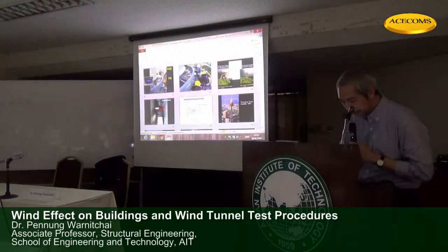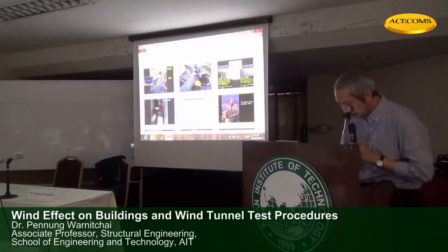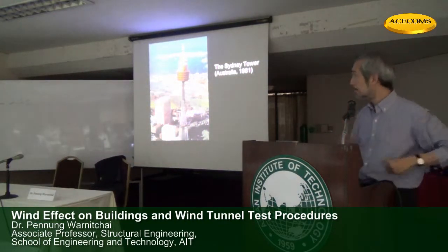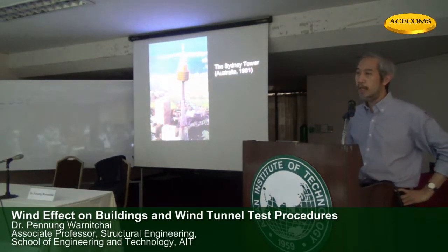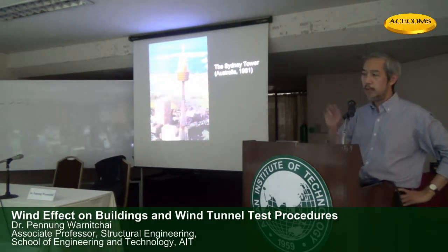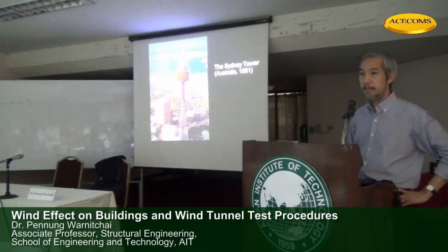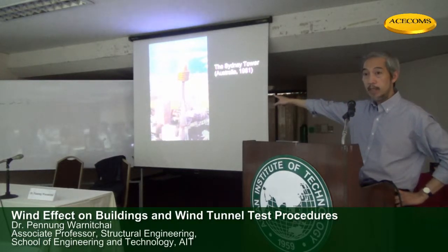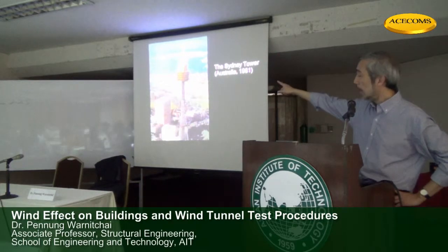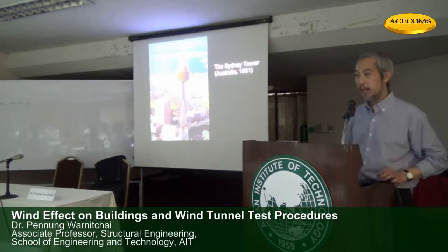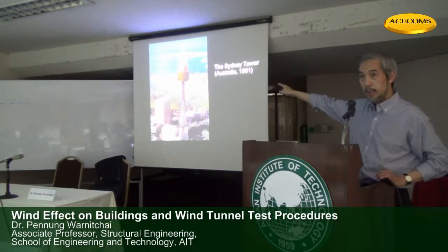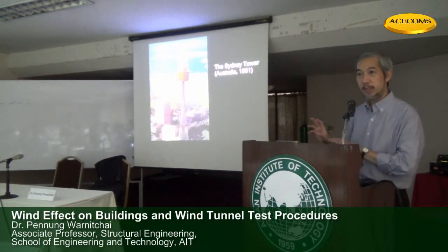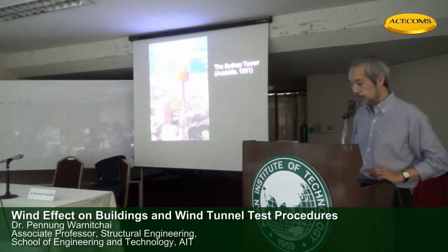Okay, come back here. Now, not only this one, actually most observatory towers have this kind of damper. This is the Sydney Tower in Australia. They have a ring type dual mass damper on the top, one unit, and in the column another one unit, to prevent the first mode and second mode, similar to the tower I just showed.